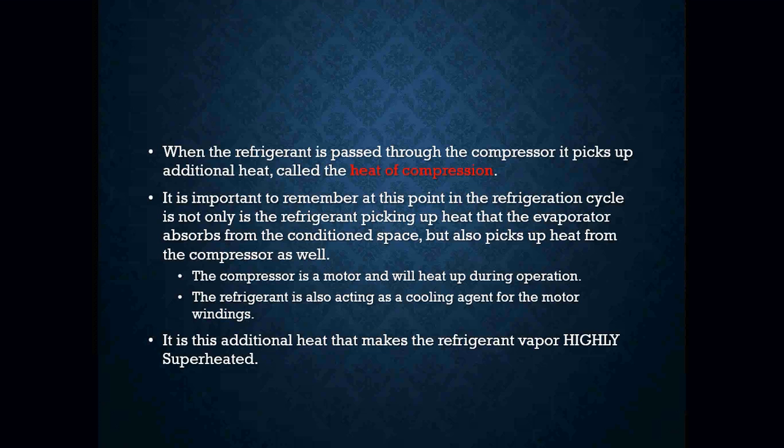With the addition of that heat, the refrigerant becomes highly superheated. We are now ensuring that the refrigerant leaving the compressor is 100% vapor by having it in a highly superheated state.